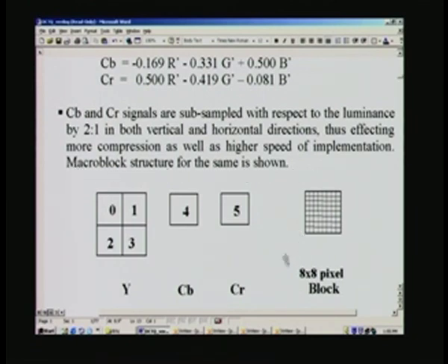So, now what we have seen is a picture, the entire picture that you saw right at the beginning, the parrot, which is actually 1024 by 768 true color. That means you need 3 bytes for representing a color in YCbCr, or even in gamma corrected RGB in the raw format, you need one byte for each of the color components.